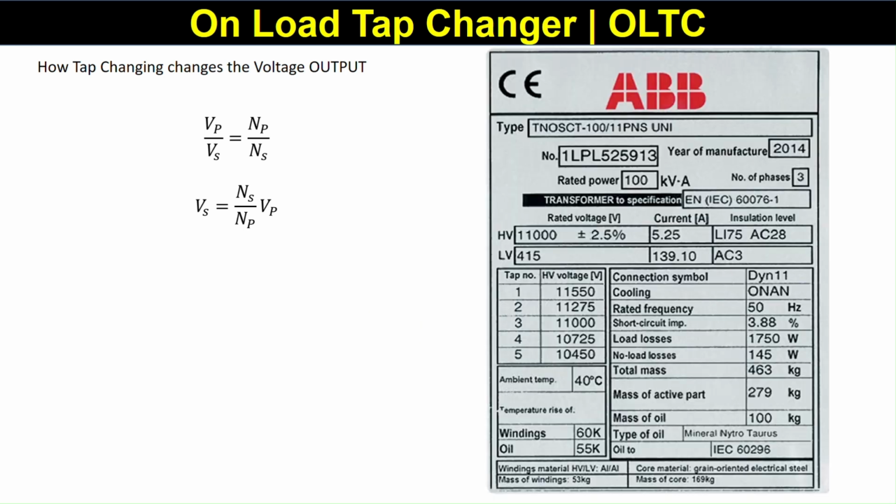Okay, this is the nameplate of one of the ABB transformers. You can see on tappings there are 5 taps on the primary, high voltage side, and each step is 2.5% of the primary 11 kV high voltage side voltage. Now I can use the same nameplate in ETAP, and you will see how voltage is controlled.